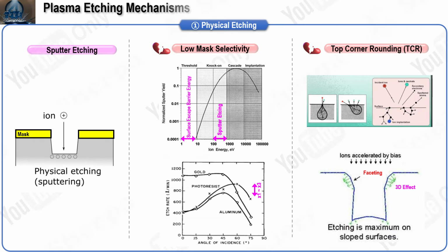There are 4 basic low-pressure plasma processes commonly used to remove material from surfaces: sputtering, pure chemical etching, ion energy-driven etching, and ion inhibitor etching. This slide defines sputter etching, and highlights its 2 defining limitations. Sputter etching is a physical removal process, where ions, accelerated by the sheath, strike the surface and transfer momentum to eject atoms through a knock-on cascade. The bombardment is directional, so features follow the arrival direction, and the profile is strongly anisotropic.